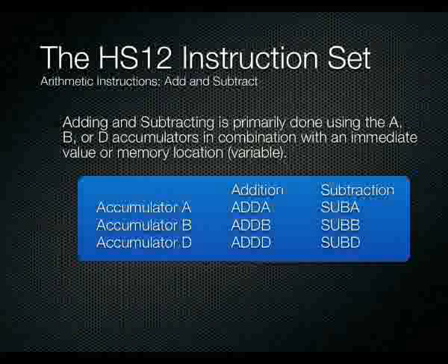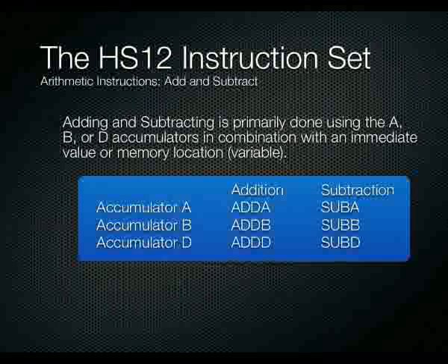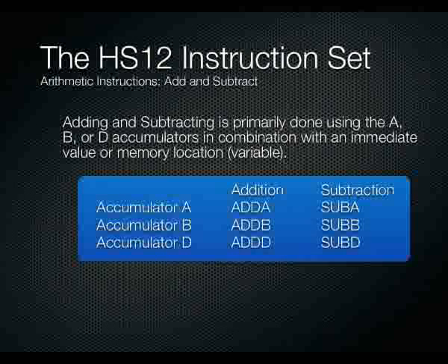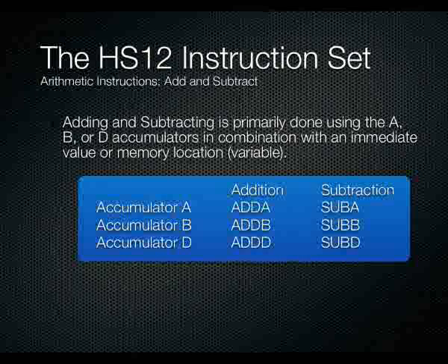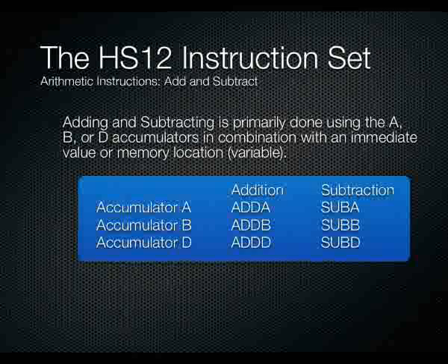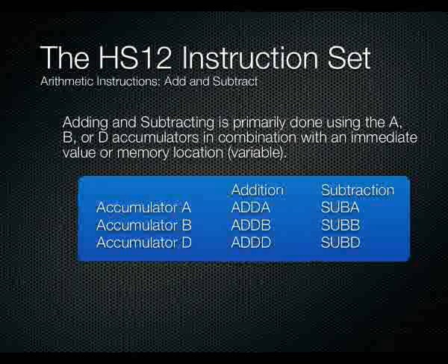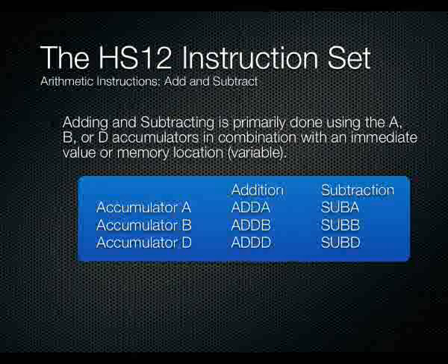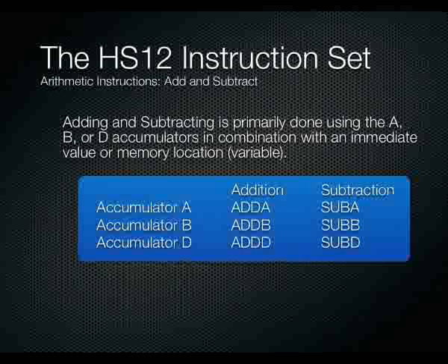Adding and subtracting is primarily done with accumulator A, accumulator B and accumulator D. You can also do addition and subtraction with the X and Y index registers, but that's a more roundabout way and a bit beyond the scope of these lectures. If you want to use those, look them up in the instruction set. I'm primarily going to focus on the basics with accumulators A, B and D.